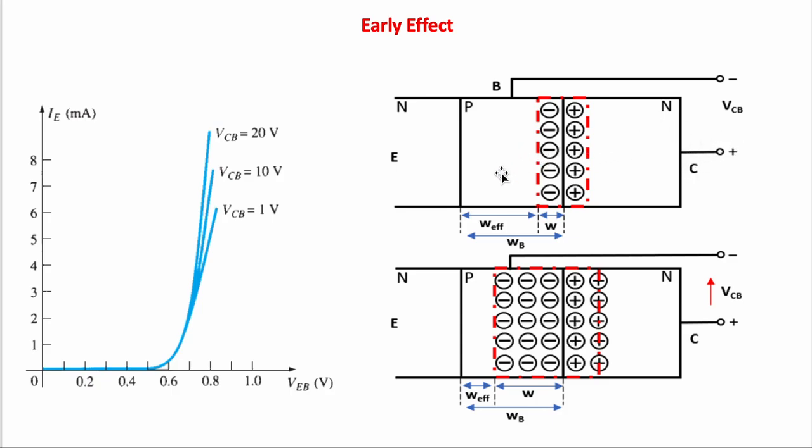For the base, it will be more negative, so the holes will be attracted to the base terminal, which results in an increase in this depletion region.